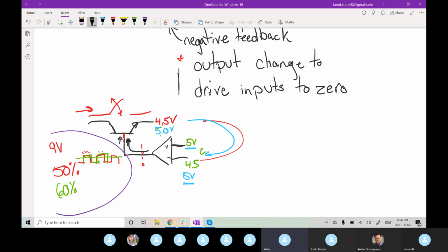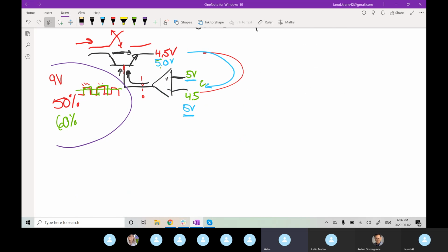Yeah, so there are different amounts of current to the base of that transistor that make it operate like a variable resistor, right? So the voltage drop across it will be different. Across the base-emitter and the collector of the transistor. Okay. And that's why they get hot.